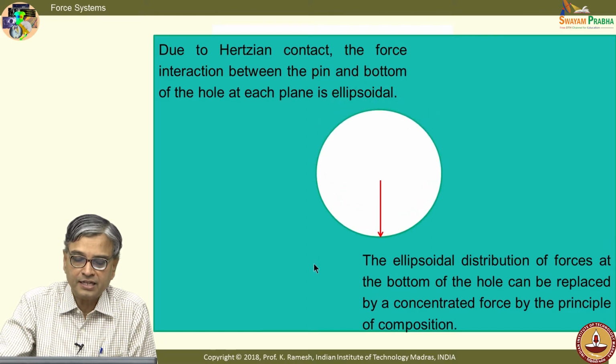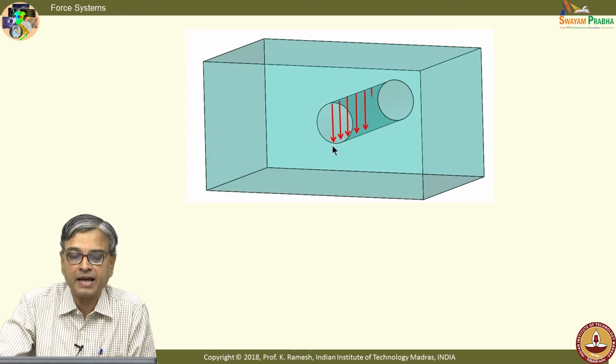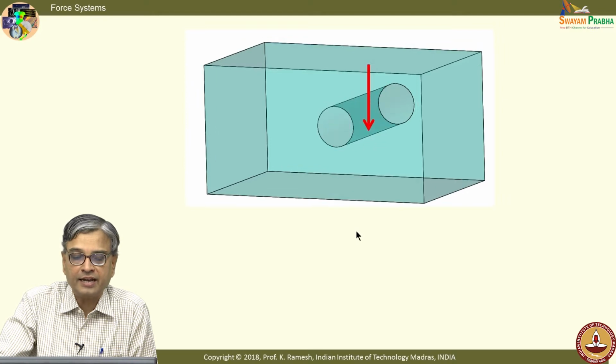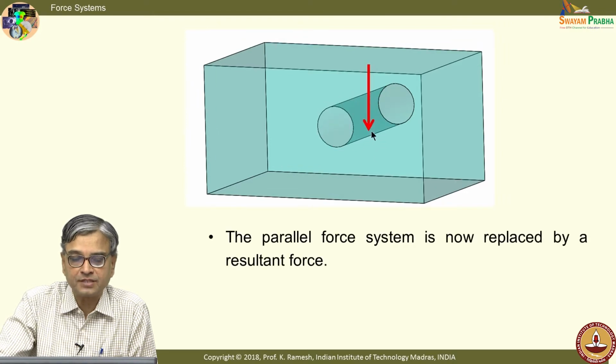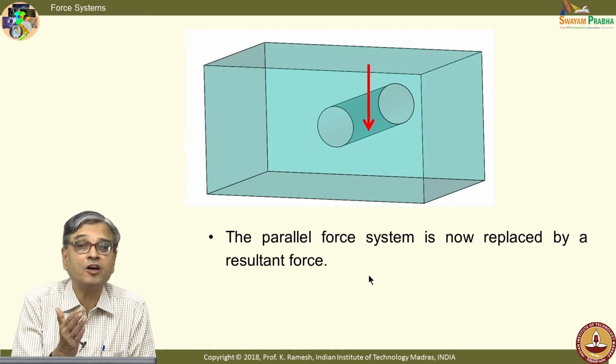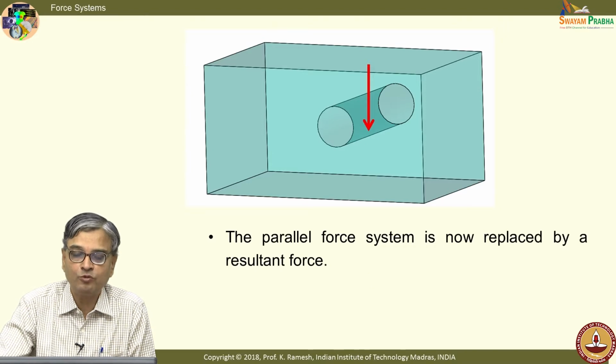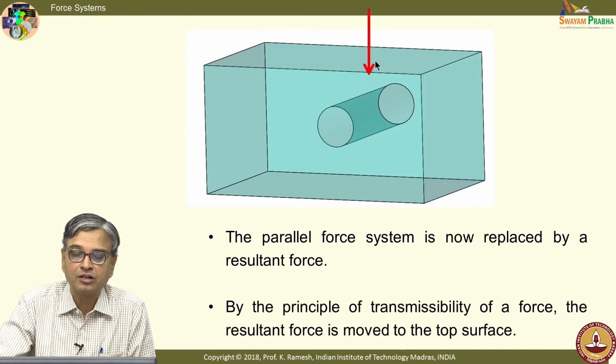And when I see this for every other plane in the pin, I would have essentially a parallel force system. I can take a resultant of this, which is simple to do, but the force is acting only at this point, and we have learnt a very powerful principle of transmissibility of a force. So, by that I move the force to the top end of the beam.